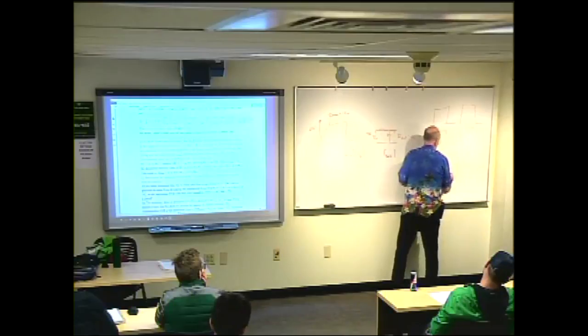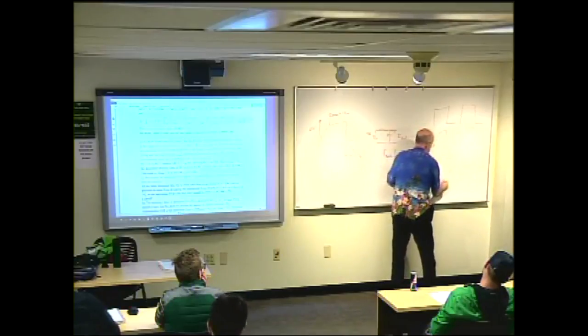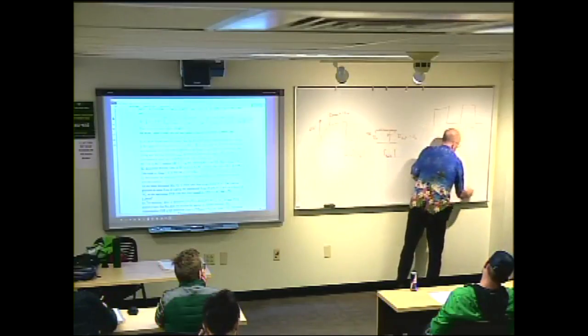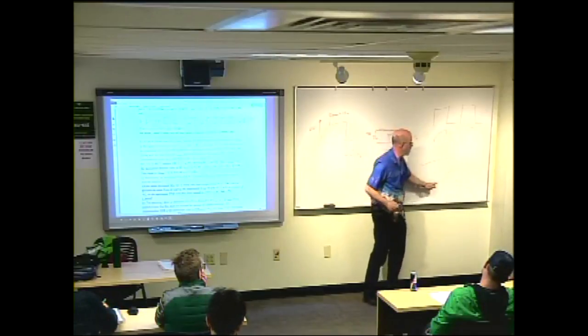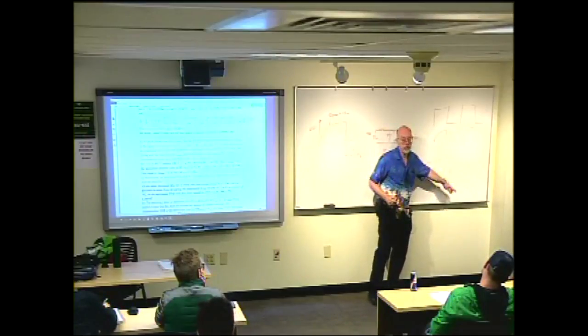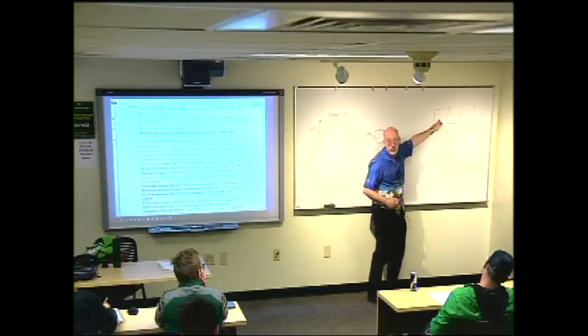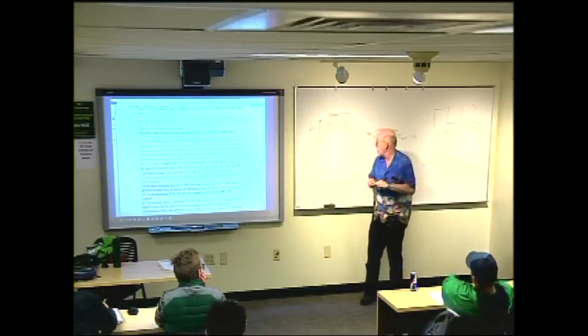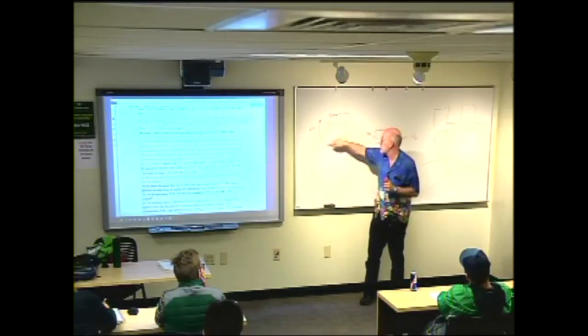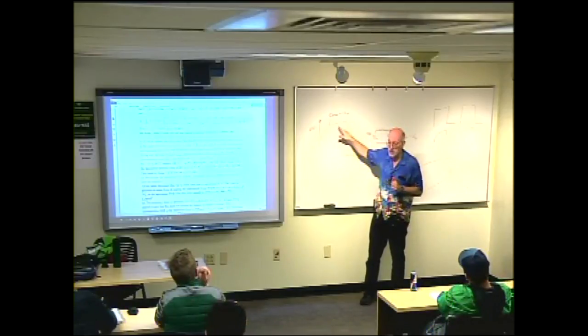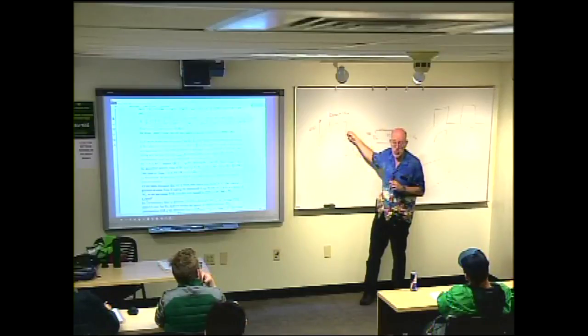the output from the triangle wave would probably look pretty close to what went into it, because these are slow transitions. They're low frequencies. This has more high frequencies in it. This edge has more high frequency content than this edge does. So actually this one is the one that's more likely to be distorted. It's the faster, more rapidly changing signal.